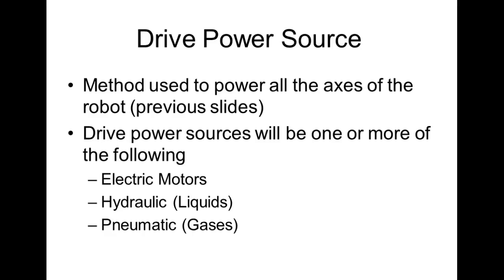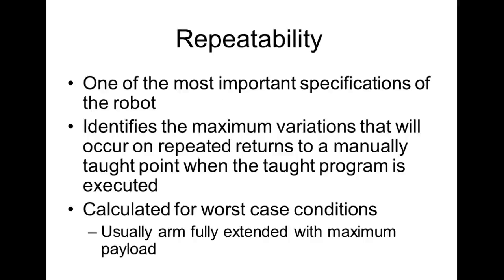Drive power, are we okay there? Electric, hydraulic, and pneumatic. These are just the robots, right? Repeatability, everybody okay on that? Usually the smaller the robot, the better repeatability it has. The bigger the robot, the worse it has, because it's trying to move all that mass.